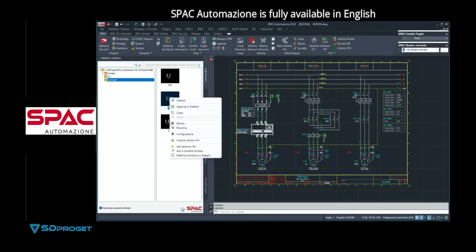Then I have to press redefine symbol on the drawing. So if that block was already drawn on 100 pages, it is redrawn and updated with the line. Okay, so with the modification that I applied, clearly the slide should also be updated, so the preview that I use to see the block. So this is the command you use when you want to make a change to a block already made.